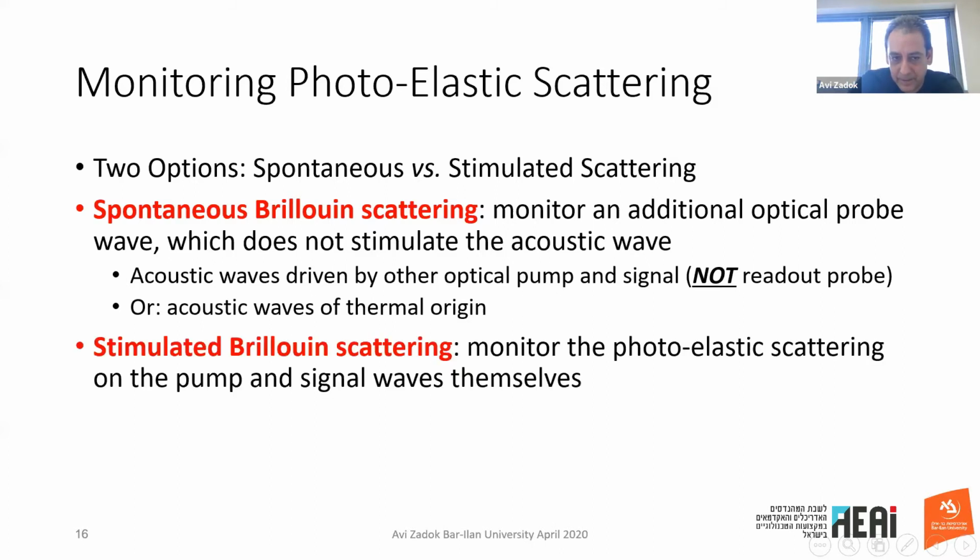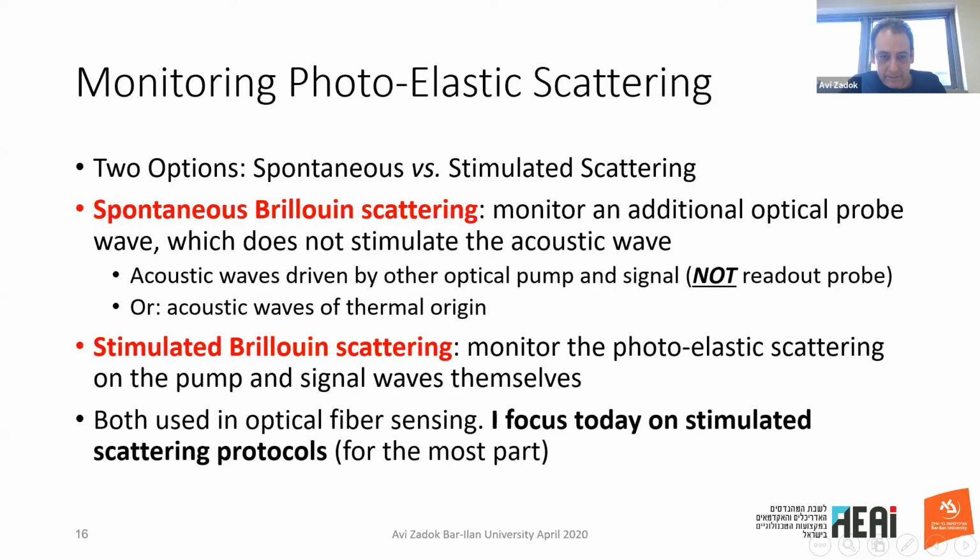In stimulated scattering, on the other hand, we observe the effect of the acoustic wave on the same pump and signal that brought it to life in the first place. So there's some kind of a feedback here. It's the pump and signal that make the acoustic wave happen in the first place, and the acoustic wave in turn is modifying the exact same waves. And this is what we're going to look at. Both protocols are being used towards sensing, but in what we speak of today, I will dedicate most of the attention to stimulated scattering.